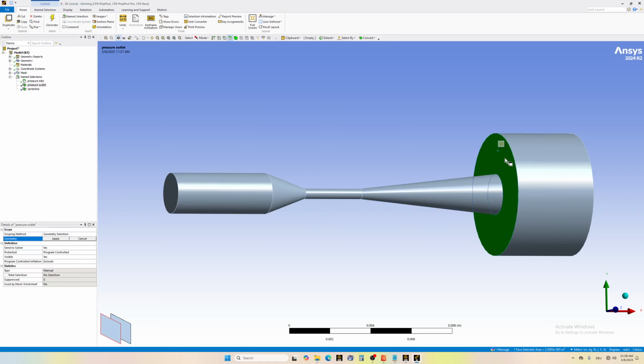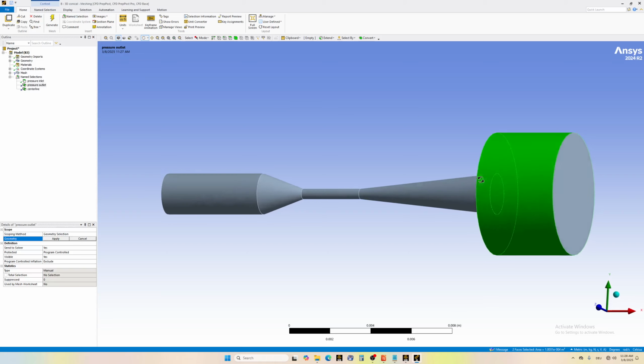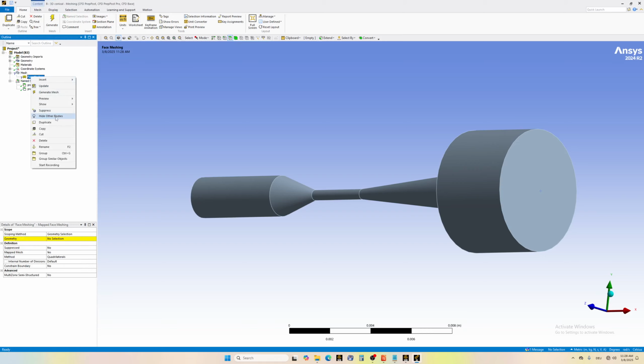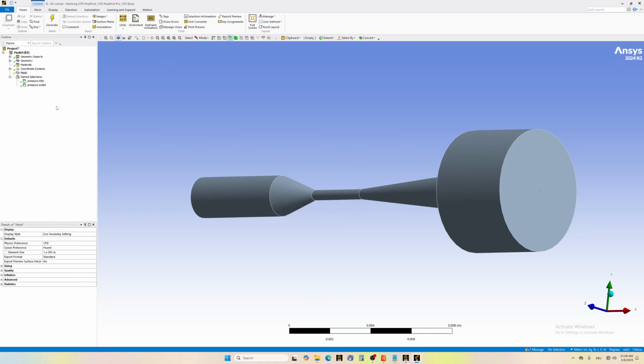So if you click this one and keep Control pressed on the keyboard, now leave the control, don't press Control anymore, rotate, all right, and single select, again press Control on the keyboard, and you have three faces, so you have it here. And of course we don't have a center line anymore, we can delete it. All right, now at mesh we can delete this one just to avoid any confusion.